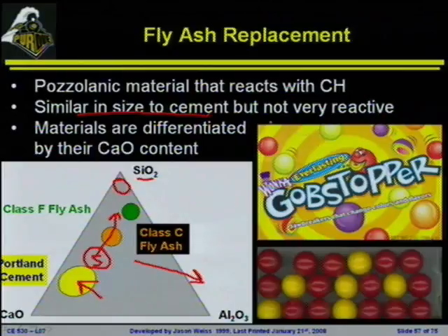But that's a very specialized form of fly ash called ultrafine fly ash, and it's typically going to have an extra process, centrifuge or something like that, to try to separate out the particle sizes. Most of the time, we're only differentiating the materials based on their CaO contents, and this is going to be mainly the difference between the C and the F ash.